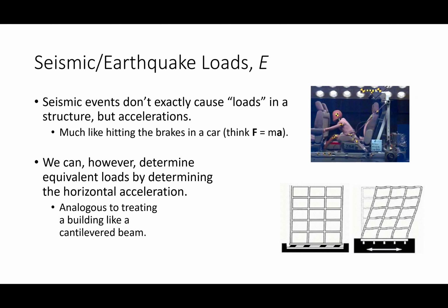Last thing I want to mention are earthquakes. Earthquakes are not something that we need to worry about here in this region of the country, but it's not to say you don't worry about it at all. The thing about earthquakes is you don't apply a force to a building in an earthquake. There's no earthquake monster pushing on a building, okay? Instead, with earthquakes, you have accelerations. So what's happening with earthquakes is the ground causes the building to accelerate.